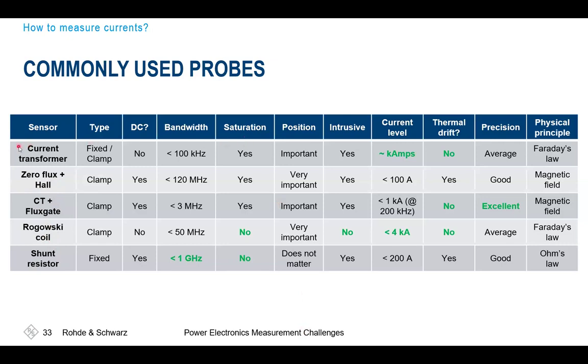Basically, standard current transformers could be constructed for kiloamperes, but you'll have to ensure you have a test position also for these others where you'll use clamps. They are quite intrusive, so you'll always have to add a certain amount of wire to be able to connect the probe, or you'll have to use the connection cables to your inverter.